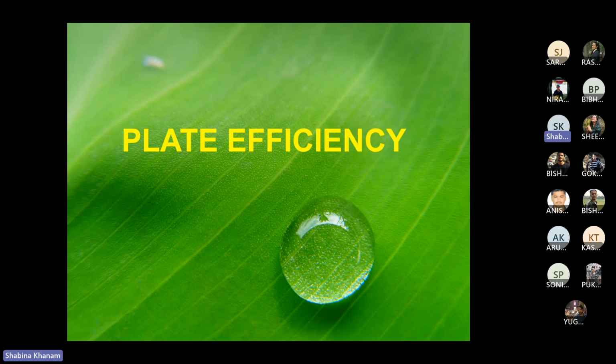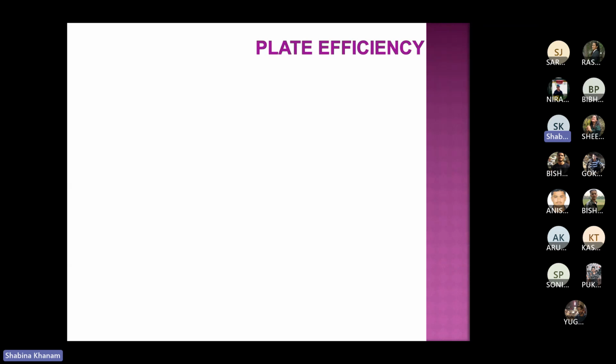So now we will start another topic in this distillation column design, and that is plate efficiency. A few preliminaries of this plate efficiency, you must have already read in your mass transfer course. And when we consider plate efficiency, why is it important? Because when we calculate the number of trays from any method like McCabe-Thiele, Hengstebeck, Erbar-Maddox, whatever method we consider, it gives us the ideal number of trays.